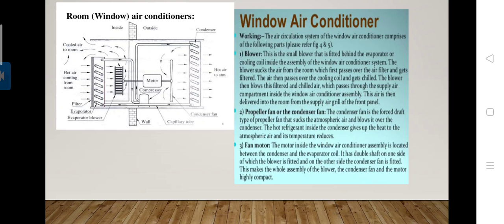The window air conditioner should be located on the north side so that it does not get direct sunlight. For a room where there is no choice of location, if it is exposed to west or south and the unit will be directly exposed to the sun rays, in such cases shade must be provided so that it is not directly exposed to sunlight.